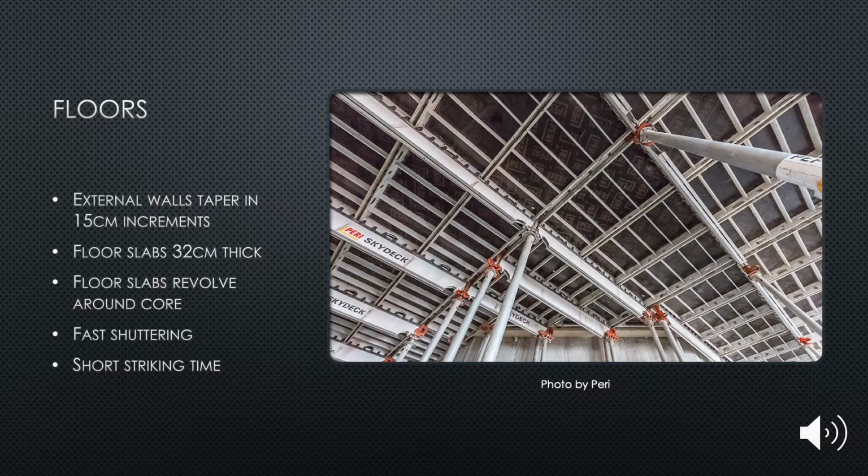A sky deck panel slab formwork was used for the slabs to ensure fast shuttering times and short striking times were achieved. This sky deck panel you can actually see from the image on the slide, which is what they were using for the project.